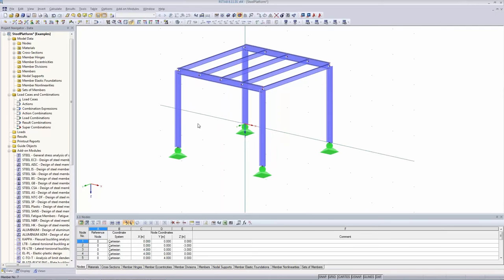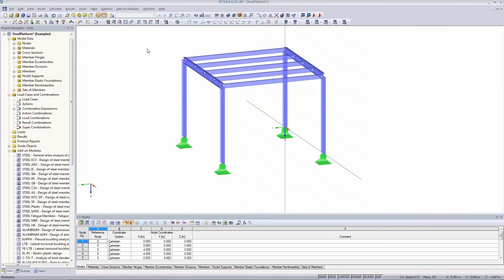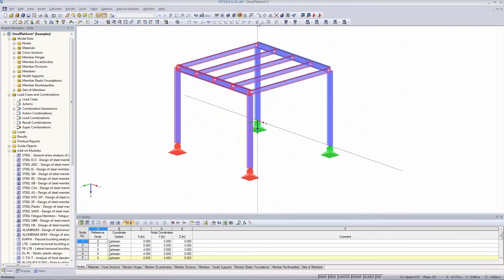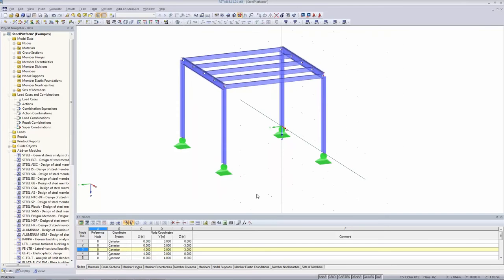I'm going to copy the whole thing. So what I want to select is this part, the other way around. When you go from right to left, then you select everything that you are crossing. And I can use the copy option again, or you could use copy, but you can also use drag and drop. So I can just take this by clicking with the left mouse button and can move it everywhere. And when I use the control button as well, then I can easily copy it.